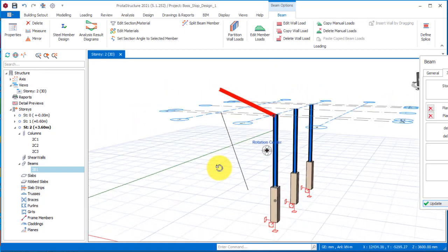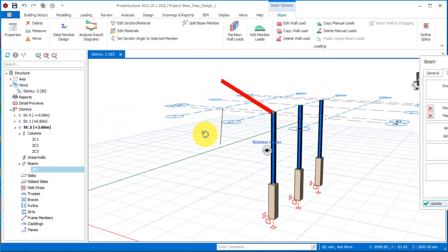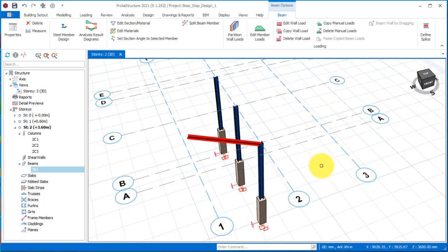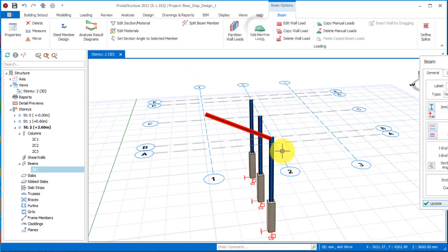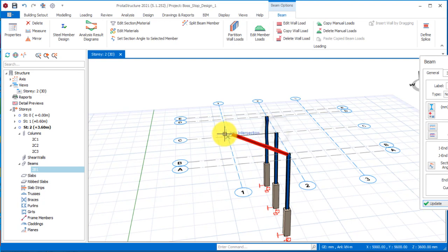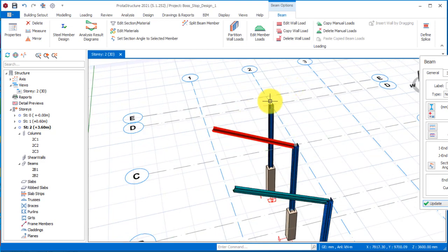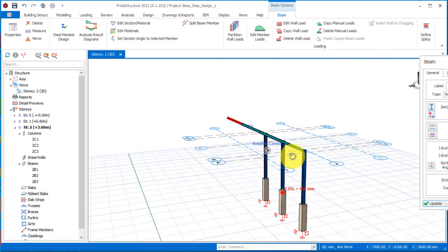All right, so this seems to be nice. If I want to lift it higher again, I can just make it 1200 millimeters, just like this. Update. Okay, so I should go by this. All right, after which I will just have to close this dialog. After closing the dialog, I will select this beam, click on its property again. Then I'll pick this point and this point to be able to place the cantilever beam as it connects to this middle stanchion successfully, just like this. Okay, so I am done with this side.